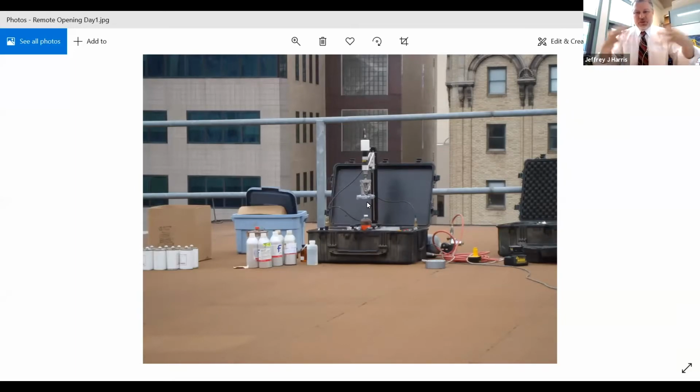You're doing one of the most safe things you can do with a potential peroxide containing material with a remote opening, but the lid won't come off, right? So now you're spending all of this money on a hazmat bomb squad crew, and you're not going to be able to get it open to stabilize. So, do you have the ability to drill into this container? And do you have the risk appetite to drill into this container from where you're located with the material?